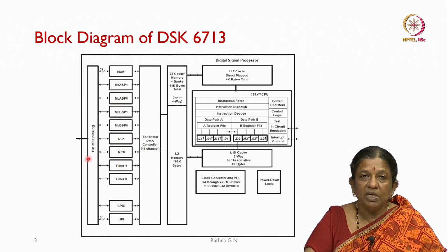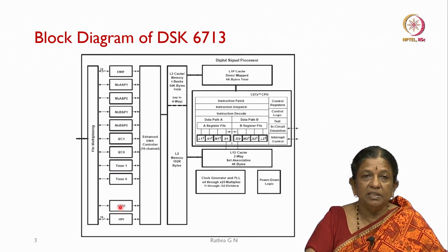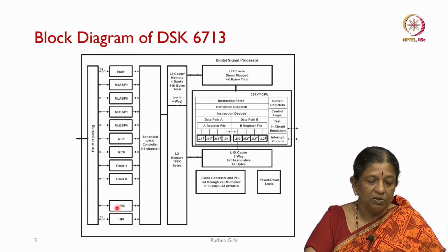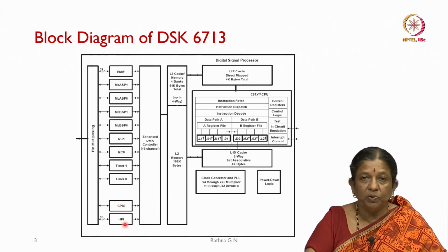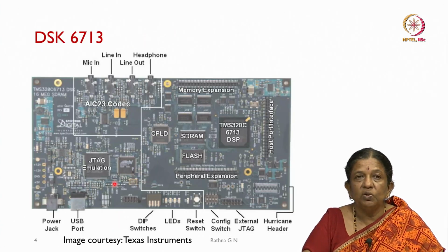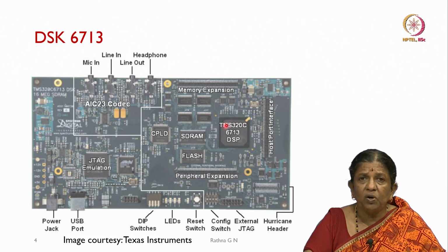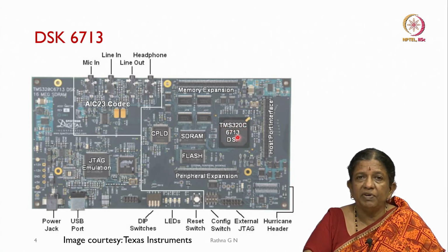Using the timer we can interface with the external world, and this is the GPIO which is connected to the board, and we can also have a host port interface using USB. This gives the overall picture of the board. We have the DSP processor here, the TMS320C6713 DSP, and then we have the SDRAM.